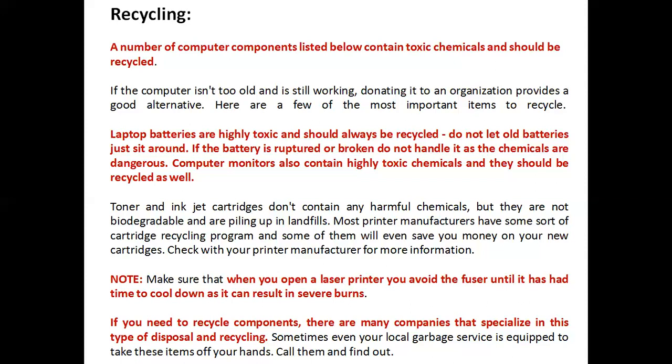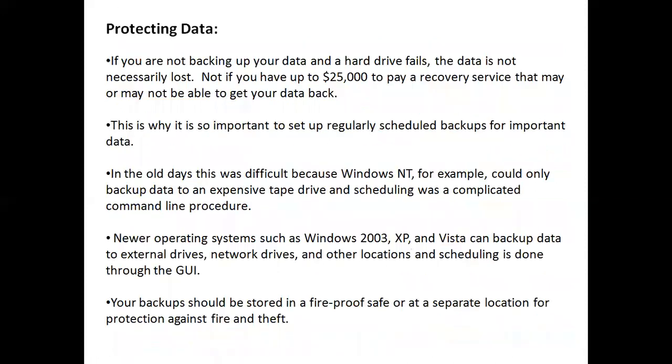If you need to recycle components, there are many companies that specialize in this type of disposal and recycling. Sometimes even your local garbage service is required to take these items off your hand. So you can call them and find out about recycling of electronic components. So your battery is very dangerous, monitor is very dangerous, and laser printer is also dangerous. Whenever you are opening a laser printer, you should avoid the fuser. Otherwise, you will feel severe burn.